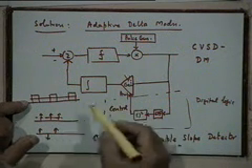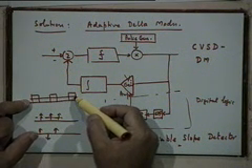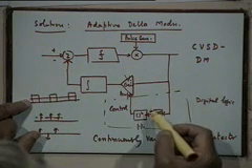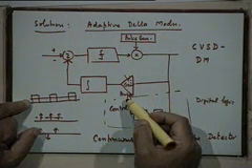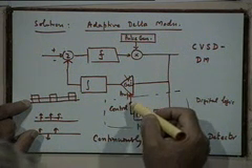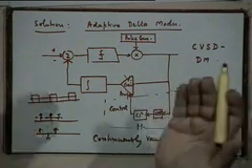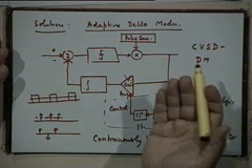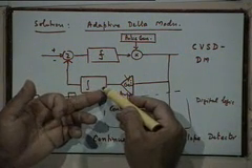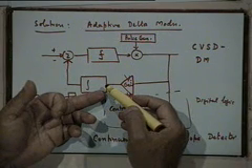So if this happens, you will get a reasonably large average positive value, and that serves as a signal to the amplifier that I must increase the gain, so that the steps will increase. And the gain increasing means the step size will increase, right?